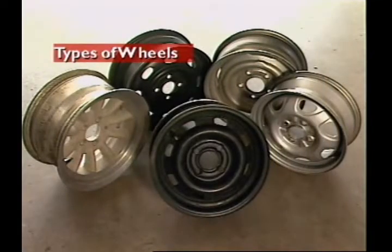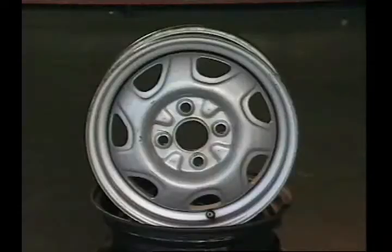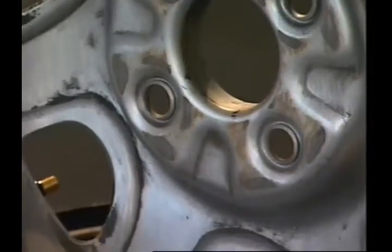This section examines types of wheels. Wheels must be strong enough to carry the mass of the vehicle and withstand the forces that are generated during use. Some are made from steel. They are pressed in two sections: the wheel center, with a flange or disc that is drilled for the wheel fasteners, and the rim. They are then welded together.